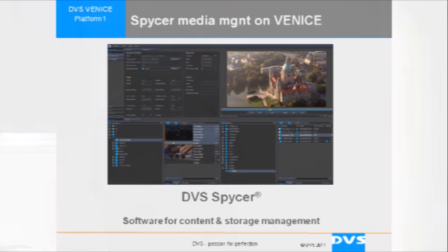You have this tool also coming with the box. You can select how many channels you have in your box. So it first browses how many channels you have. Then you can build groups between them, playout groups, ingest groups, and so on. And you can build these split views. You see always what's going on in all of your channels. And you have them absolutely in sync. It's internally synced. So it's just necessary to feed a genlock or a sync signal to one of these channels. All the others will follow and will be absolutely in frame sync.